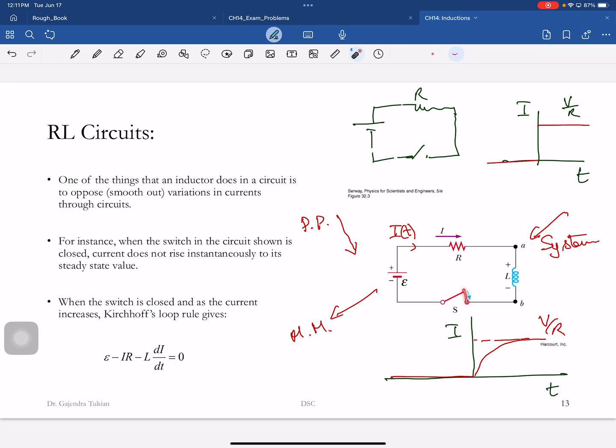Well, you close this guy. This is a closed loop. Does anybody have anything to say about a closed loop? That's right. Mr. Kirchhoff tells us that the sum of the voltage changes across all elements in a closed loop will add up to 0. That's the physical principle that's going to give you the equation. All right, so we close the loop. Let's start here. We'll go across this, plus C.